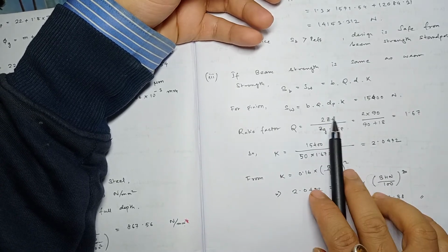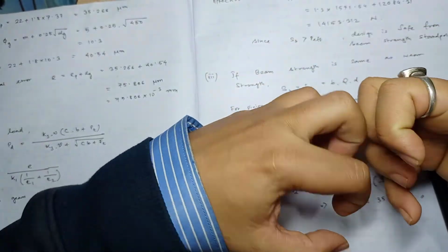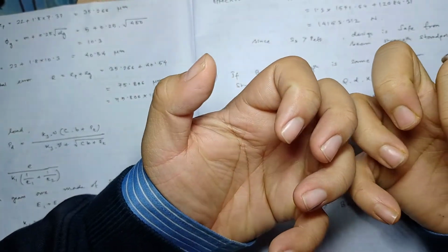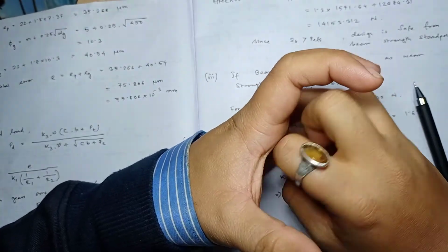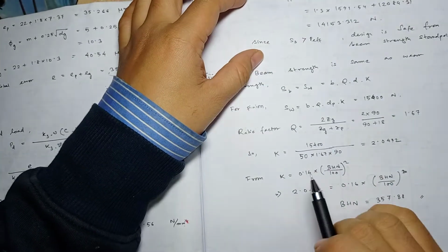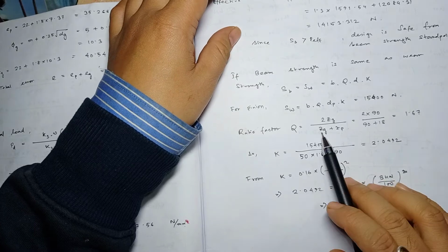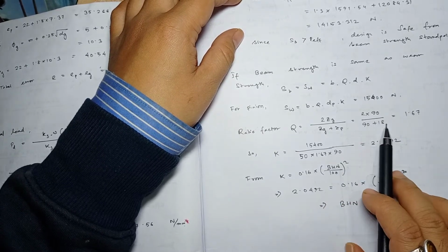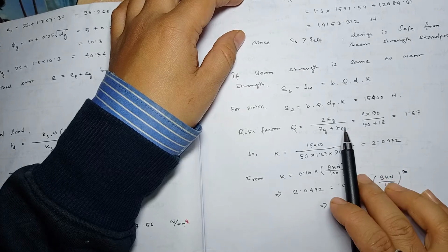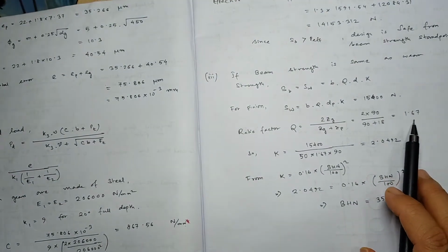For external gears, both are connected like this, in this manner, so that is your external gear. And if one gear is inside another gear, that is called an internal gear. You don't have to worry about that. So this is the ratio factor here, which is 2 into ZG is 90, divided by ZG is 90 here plus ZP is 18. So from here you can calculate your Q value.